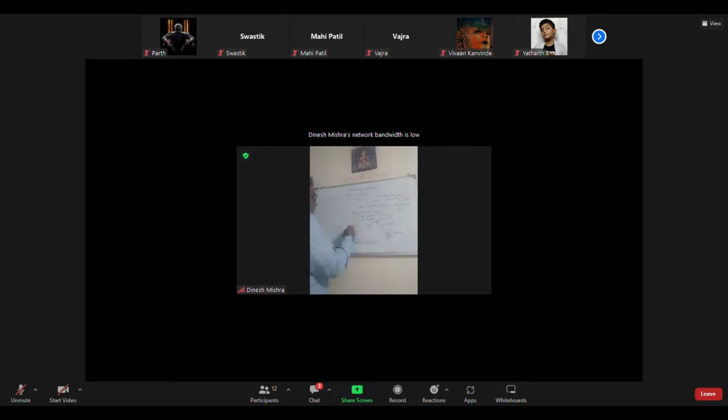The deflecting system works on the magnetic effect. Whenever a current carrying conductor is placed in a magnetic field, a torque is produced. If there is a magnet creating a magnetic field, and we place a coil inside it and give current to that coil, the coil will move. When the coil moves, that is called the deflecting force. And when the coil moves, the gravity system or the spring will produce the controlling system.